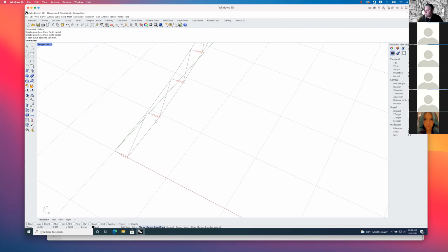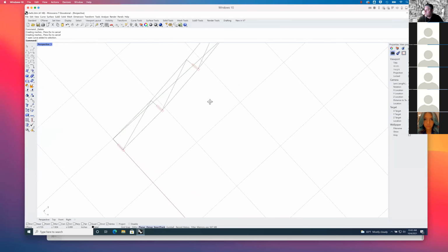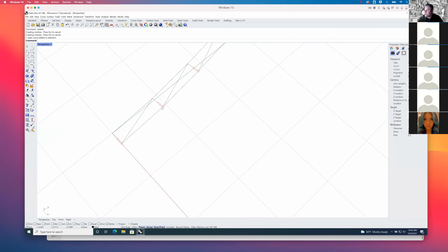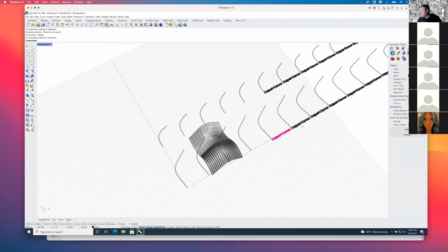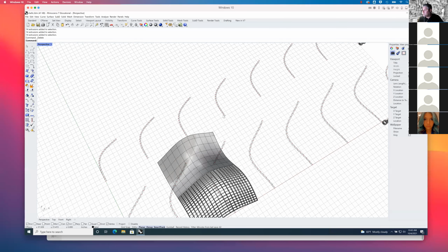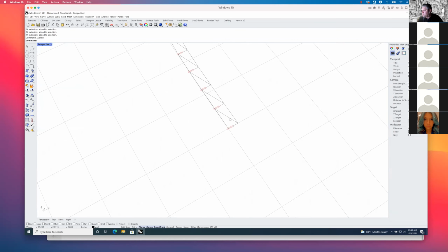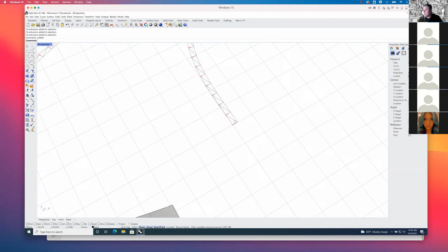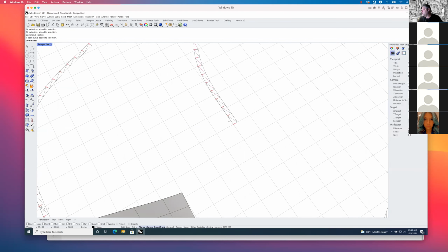And these are things that can just be cut out, right? And then cut the overall shape out. And so that gives you the U's and the V's. And honestly, there's something I really quickly have to fix here. It'll also give you the labels, the typeface labels here. But honestly, what I'm going to do is tell you to create those labels again yourself using a single stroke font in Rhino. So we'll talk about that stuff later.